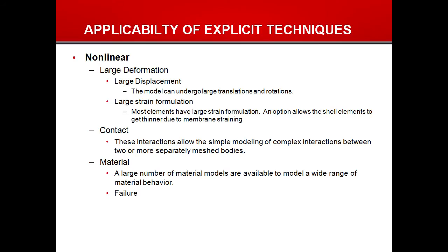Let's talk about nonlinearities briefly. Just like with the implicit codes, we divide and categorize the nonlinearities into three categories. Large deformation. Now, large deformation includes not only large displacements and large rotations, it also includes large strain formulations. Most of our element technology has these large strain formulations because the very nature of these types of simulations tends to be large strain. So we handle that. That's all part of the code, and there's no extra cost that goes along with that.